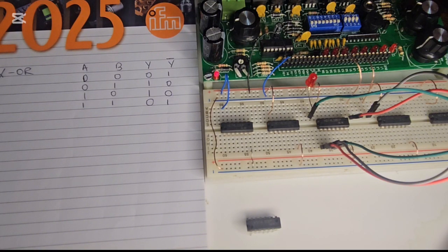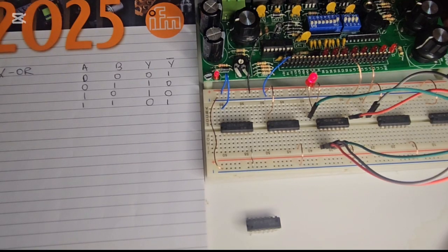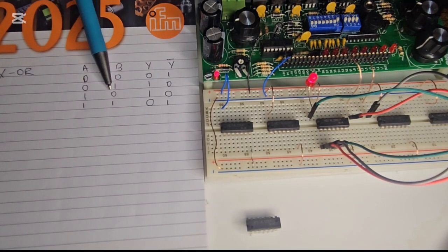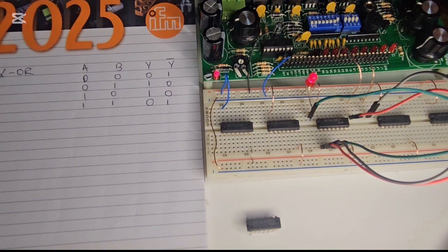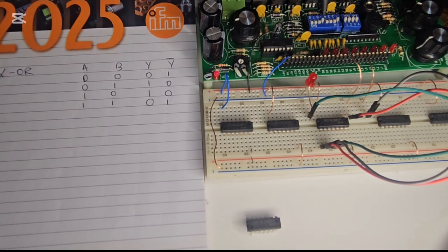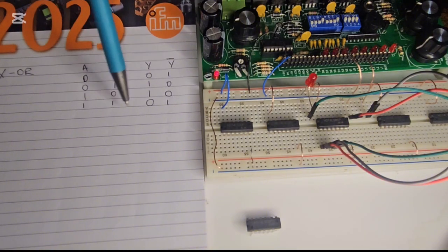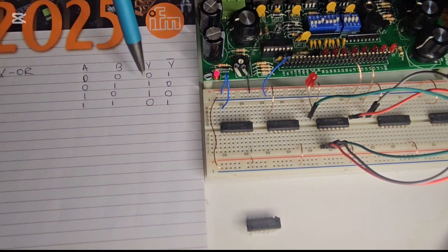Now let's make one of them on. Let's start with number 1. If I make one of the inputs true, I should be getting a true. That's correct. Now let's make both on, which is number 1 is already on. Let's do number 5. Now, when both inputs are on, which is a 1 and a 1, a 1 and a 1 gives me a 0. It matches the logic.